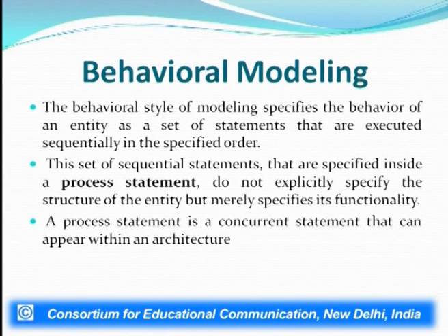Now, coming to the behavioral style of modeling, it is used to specify the behavior of an entity as a set of statements that are executed sequentially in a specific order. This set of sequential statements is specified inside a process statement. They do not explicitly specify the structure as in the case of data flow modeling, but they specify the functionality.